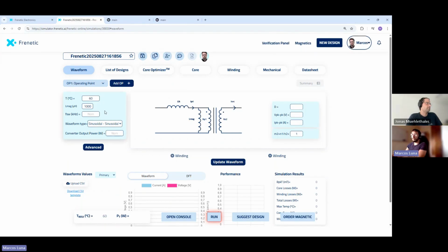Okay, and in the switching frequency, if we are talking about an AC common mode choke, the frequency of the signals is typically 50, 60 hertz. And if we are talking about DC, it's DC. So in this case, we need to put a small value. Okay, we put 100 hertz because the materials that we have here need a minimum of 100 hertz, but it doesn't matter. Okay, you put a very small value, it's fine. And that only considers the conductive losses of the winding.